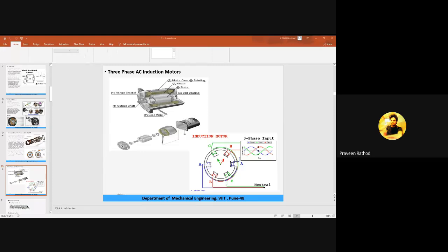Because a central driver motor with a fixed ratio encounters mechanical loss, as well as a variable gearbox, there is no possibility of operating the motor at maximum efficiency. So a simple layout of an electric vehicle is a single electric machine with the help of a gearbox and differential. You can eliminate the differential also, and use only the gearbox with a battery.